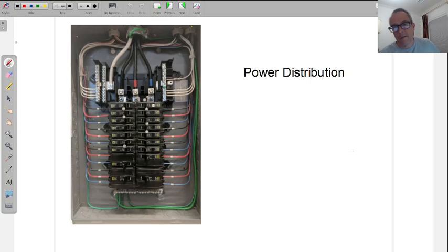Now, are you going to be opening up power distribution transformers? No, just to measure. No, you're going to be in here. You're going to be in panels. So there is where I was trying to communicate that last week. Understanding the voltages, what delta has, what Y has, which one's 480, how to understand 208 versus 120, is because you're going to be in a panel. Panel's going to look like this.